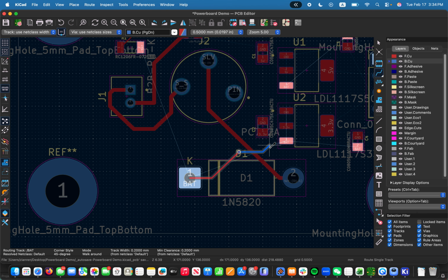But be really careful when you guys are doing vias and routing via the other side, because now you see I can't actually connect to this component. That is because this component right here is a surface mount component. There is nothing to connect to on the other side.